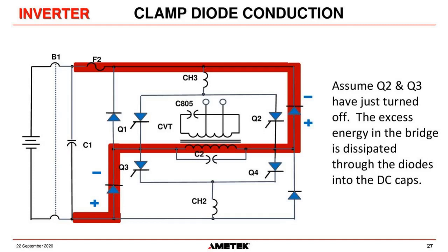So when we take temperatures of the inverter bridge, like when we test the machines, the SCRs run hottest at full load, which is no surprise to anyone. But the diodes, they run hottest at no load because they're working the hardest, and they have almost nothing to do at full load. And it took us a while initially to realize that. We always assumed everything got hottest at full load. And then we found out we need to check temperatures for diodes at no load. And if you have the manual for one of your inverters of this vintage, or actually any machines we make, if you have the test data, we record all those readings in the test data.